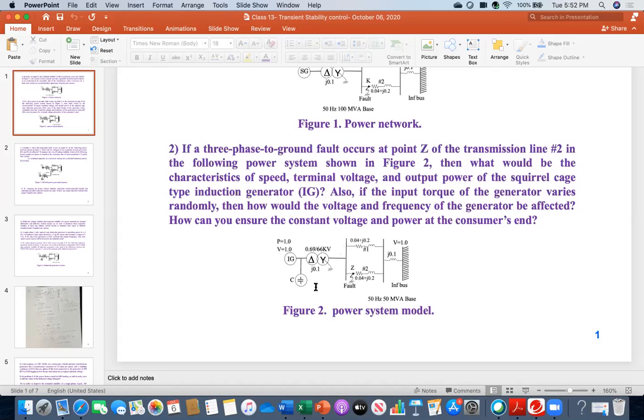this capacitor cannot do anything, because this is fixed. It does not have any controller involved. For example, a braking resistor has thyristor based control. It is fixed. When this generator system is installed, in real practice, at that time it is calculated what should be the capacity, how it will fully compensate, so that there will not be any voltage drop during steady state condition. So it will try to hold the constant voltage during steady state condition.